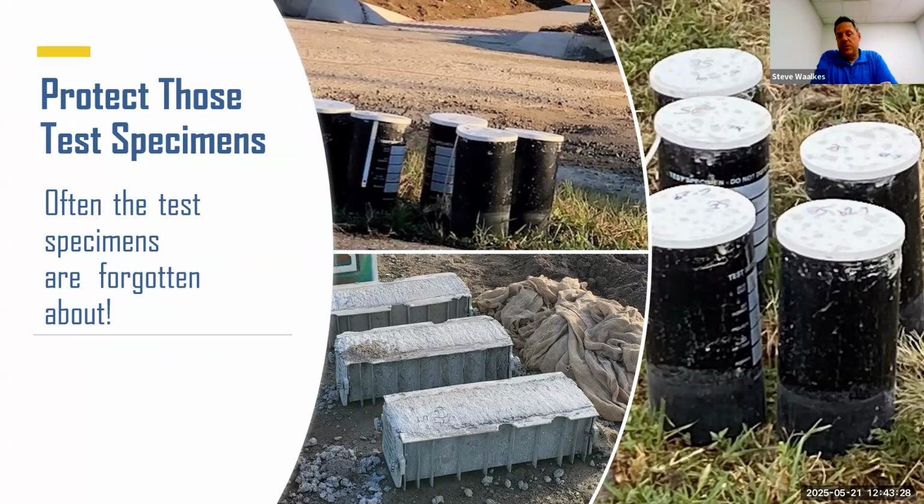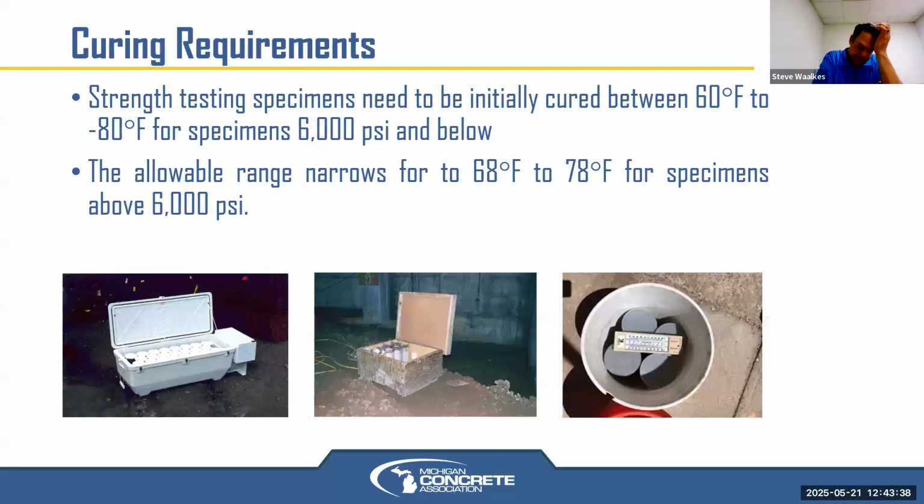Again, beams typically have just curing compound sprayed on the top or wet burlap pulled over top for curing, and the cylinders typically have a cap put on, but they do need to be picked up and brought back to the lab. Standard mixes, like I said, 6,000 psi and below as their design strength, need to be between 60 and 80 in the field.